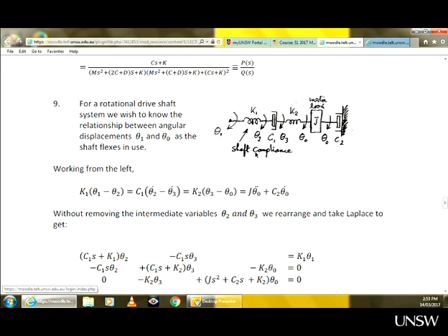But because the disk itself is rigid, it is the same displacement on the other side of the disk as well, θO. And finally, you have another viscous damper, but the cylinder of the viscous damper is fixed. It does not rotate, only this piston inside, if you want to call it piston. So you have 1, 2, 3, 4 variables, θ1, θ2, θ3, and θO.